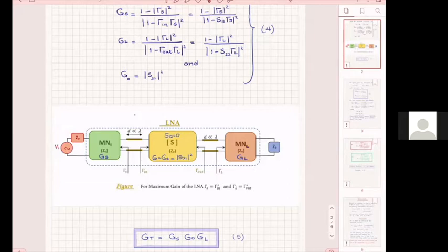However, you need to keep in mind one thing: if you develop a design using LC circuits, like lumped elements, and then you translate the same design into a transmission line equivalent, your designs with the lumped elements will be more broadband than your designs with transmission lines. Why is that?